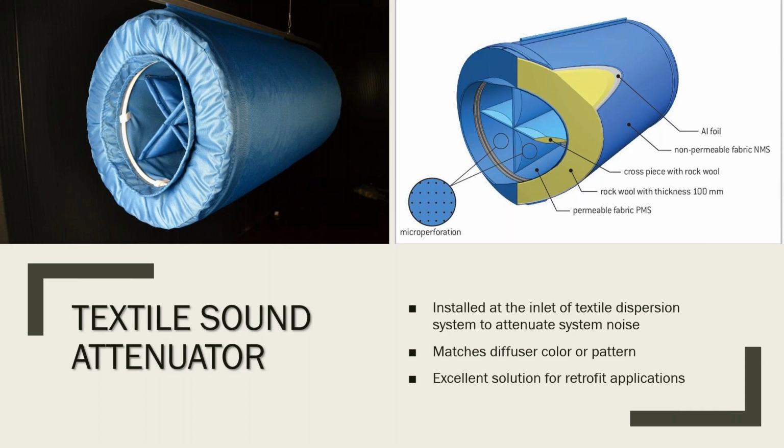It kind of looks bulky in this picture, but you can see how that opening right there is a little bit smaller than the actual attenuator. Even though I don't have a real picture showing that, if you can picture the fabric duct connecting right there at that outlet where you see the X in the middle, your diffuser will be a little bit smaller than the actual attenuator itself. It's not the most beautiful looking thing, but it does serve its purpose where you do need to knock down sound, like in a recording studio or even a library.